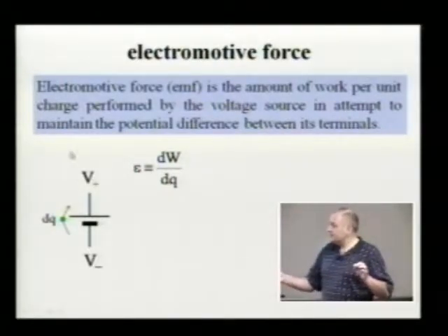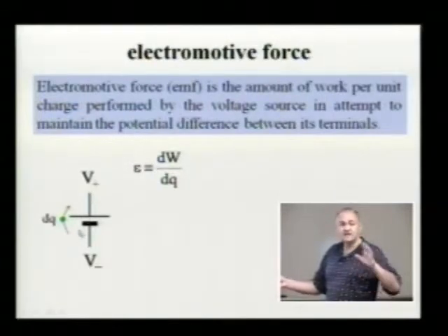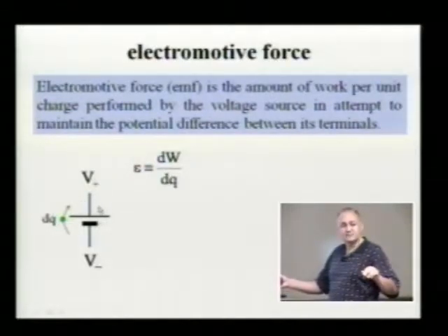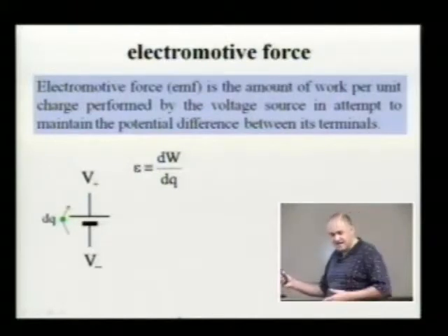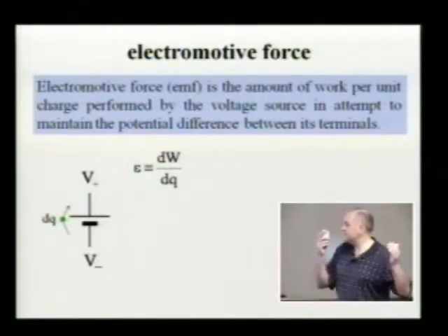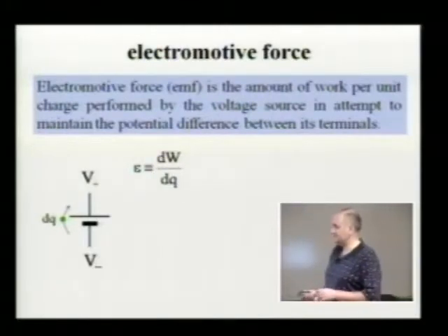Yeah, so if the loop is not closed, that charge transferred from one side to another side, which creates that electric field, suppresses the reaction, and the battery will do nothing. If we now close the circuit and we remove this transferred charge, the reaction will replenish it, all the time transferring charge from one side to another side.